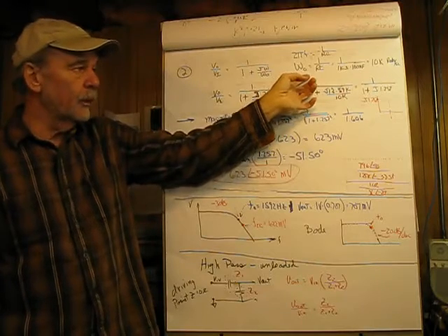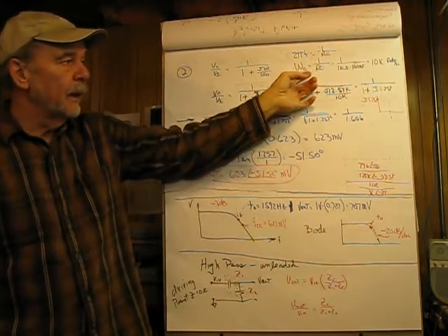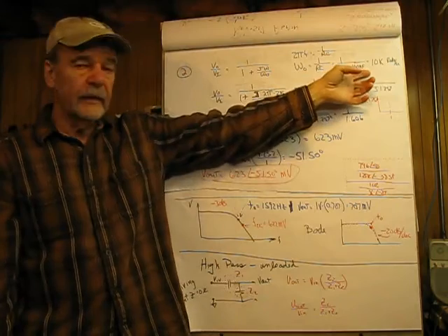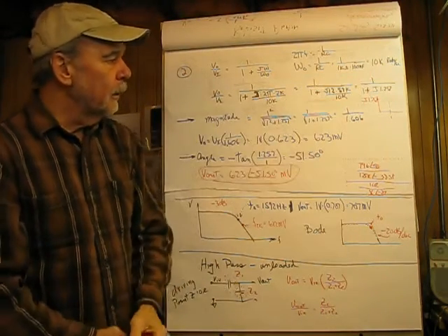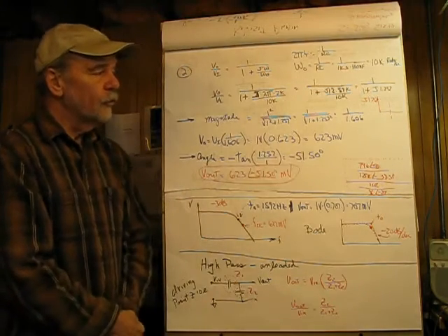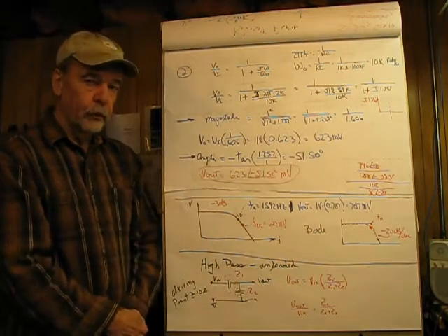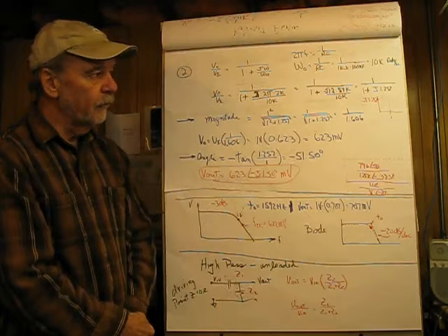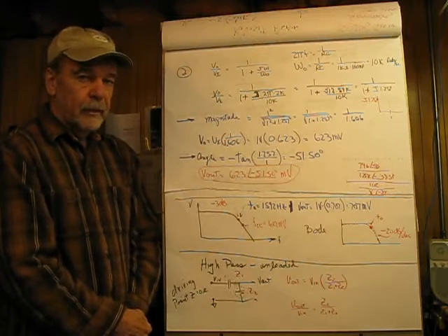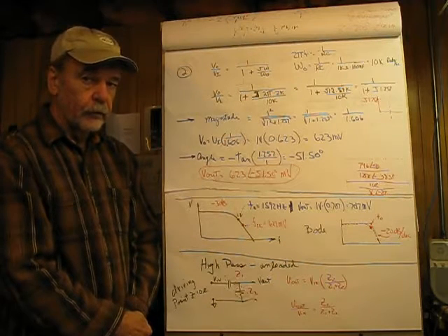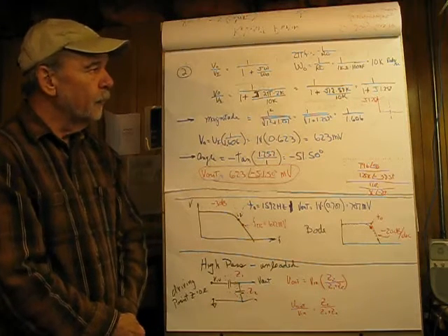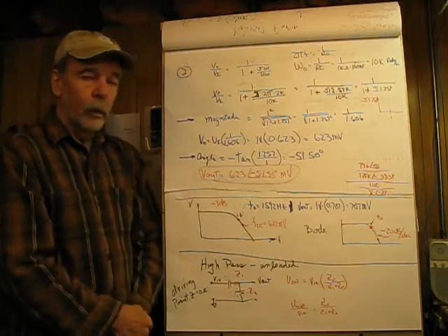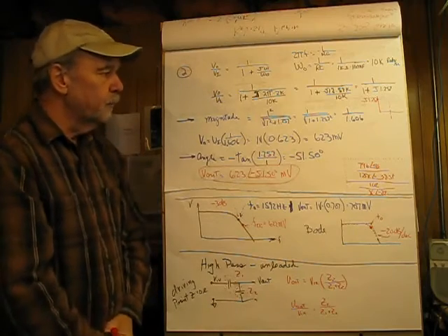So omega 0 equals 1 over RC again, and if we work that through, we find out that that is 10k rads per second. Now a radian, there's 6.28 rads per unit circle, and just think of that as that many pieces of pi times the frequency. So we have 10,000 radians per second, and that would be for our critical frequency.